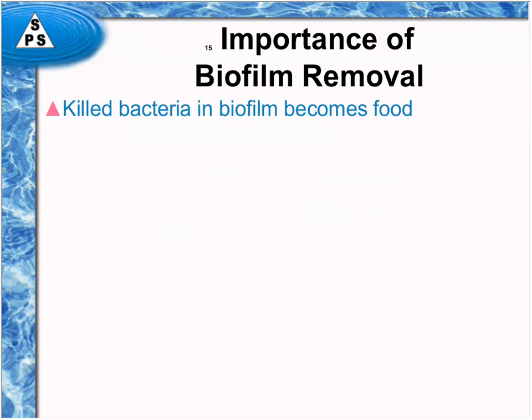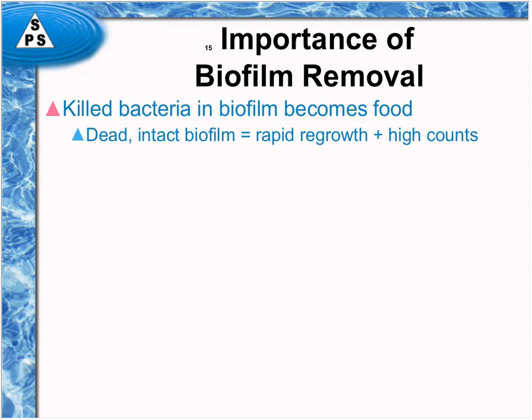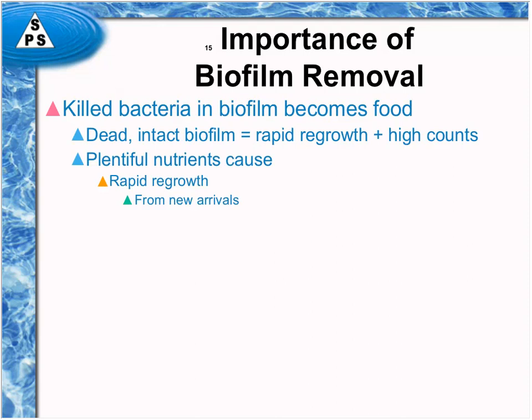The importance of biofilm removal is that the killed bacteria become biofilm food for the next guys that come along. Dead, intact biofilm usually results in rapid regrowth and high counts because there's plentiful nutrients around that then feed this rapid regrowth.